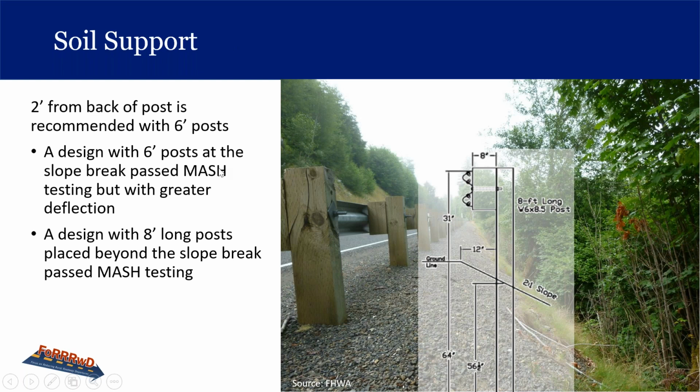A design with 6-foot posts at the slope break passed the MASH testing, but with greater deflection. A design with 8-foot long posts placed beyond the slope break passed the MASH testing.